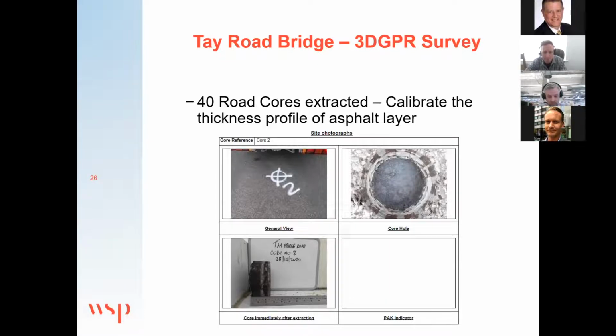Yeah. No, for me as an end user, it's brilliant because in other systems you would have to have a low frequency antenna and a high frequency antenna, so you'd have to do multiple runs. If you think about it, this is doing it in one go. That now is an advantage. So in one scan, it's looking at the thin layers very close to the surface, and deeper down. Now I know in the bridge deck, it's not too thick. So we're really reliant on those high frequencies resolving, and I'll show you the data.